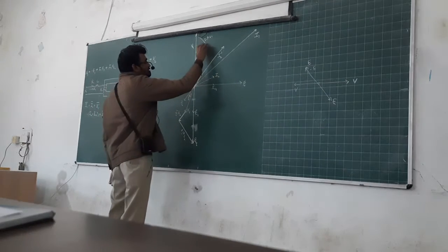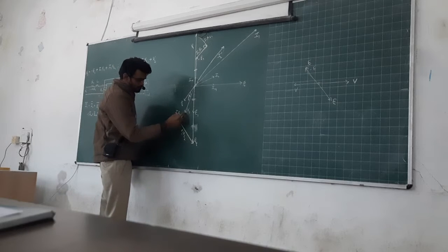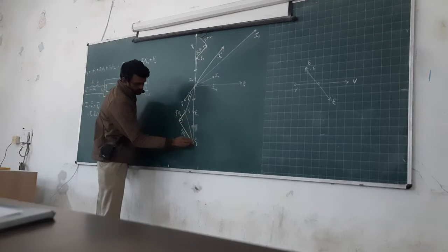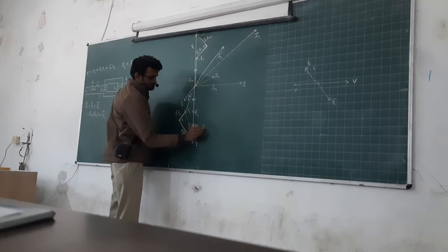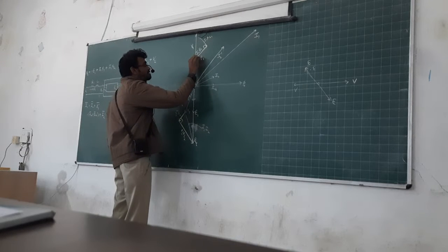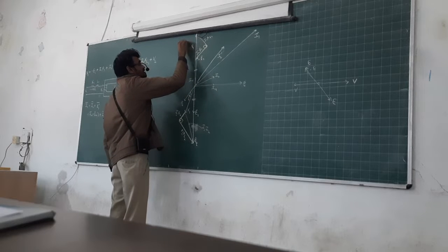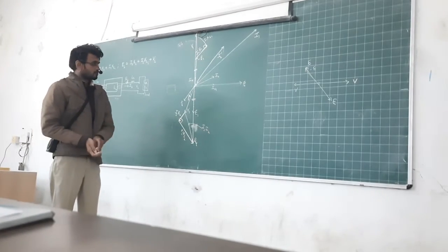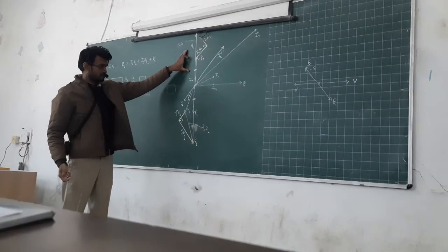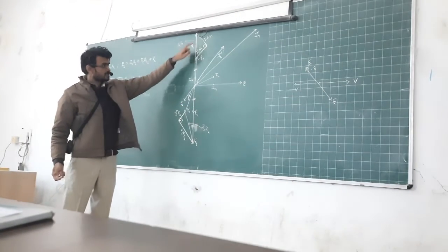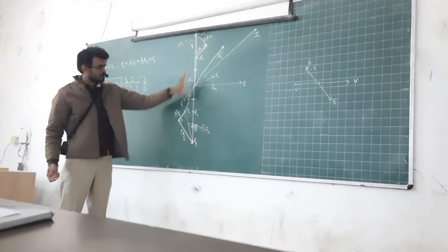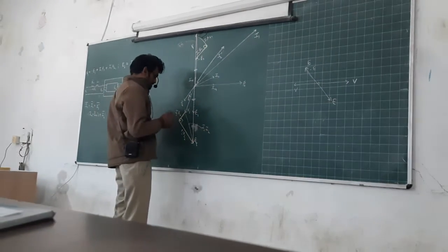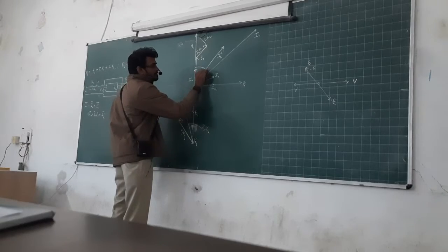Okay, and this is the complete phasor diagram. If two vectors are added together, then we will get I2 Z2. Only these two vectors. If these two vectors are added together, then I will get I1 Z1 impedance, and this is called impedance triangle. Okay, so you can see here, where is the flux? Here is the flux. These are the voltage loss triangle. These are the back EMF. These are the primary side current. And what is the angle between V1 and I1? It is what we call phi 1, from here to here.